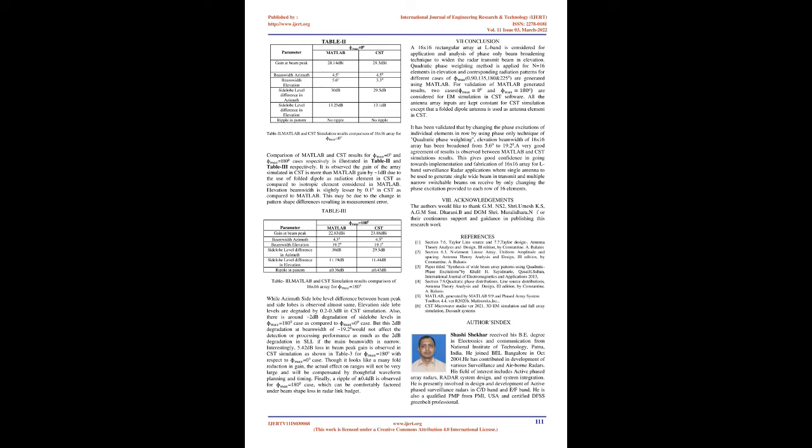For φmax equals 0°, Fig. 11 is the MATLAB simulated 3D pattern. Due to Taylor weighting in azimuth, side lobe levels are very low as compared to elevation side lobe levels, and Fig. 12 shows the CST simulated 3D pattern. For φmax equals 180°, Fig. 13 is a MATLAB simulated 3D pattern. Beam broadening in elevation is visible as expected. Fig. 14 is a CST simulated 3D pattern for the same case.